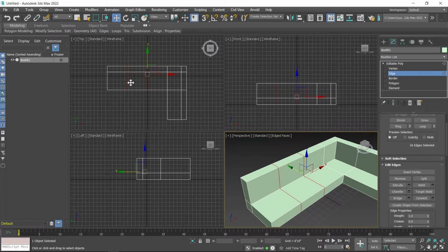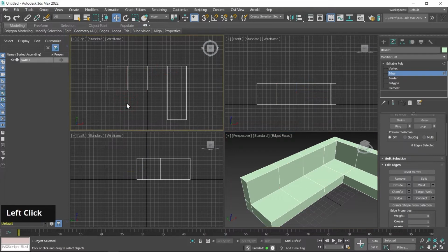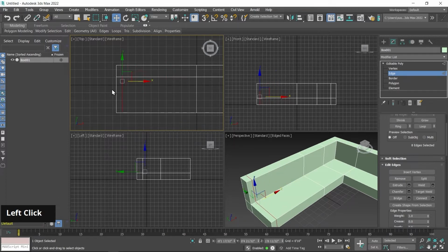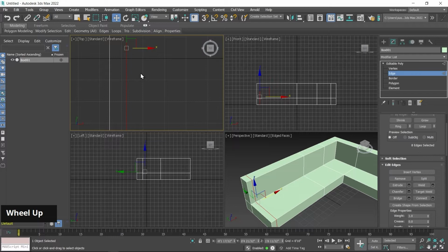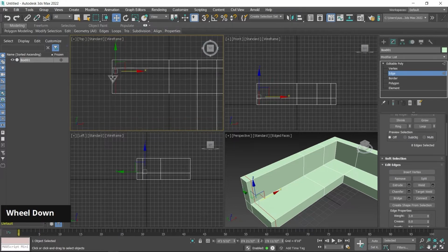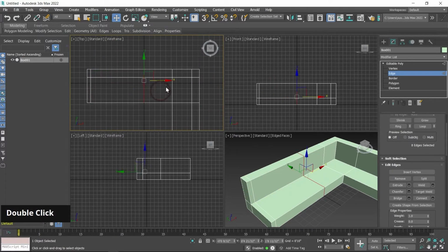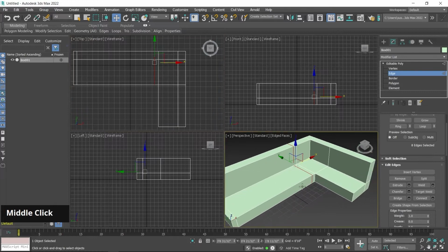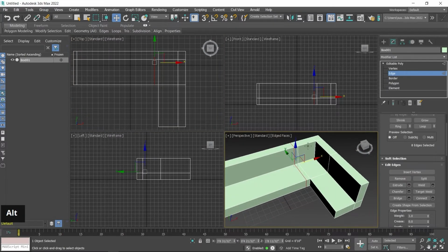In case if you want to move this edge in left side or right side, first click outside to deselect, then double click on this edge for loop selection, then zoom little bit and then move this in the corner. Distance should be like this, same as I select this and then move here. Okay, same as you have to create multiple connections on the edges.